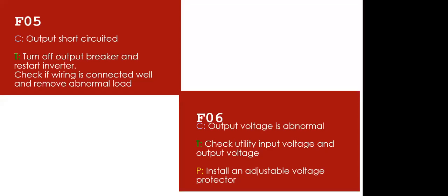After that, you introduce your output. After you introduce your output, you check all the appliances one by one. Whichever one you turn on that makes the short circuit come up on the inverter, definitely you know that is where the problem is coming from. Then from there, you separate it and continue to troubleshoot your inverter.